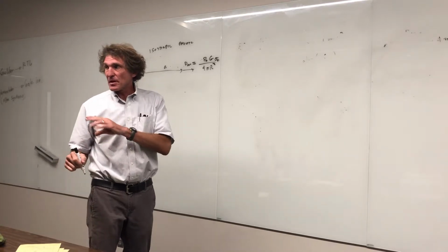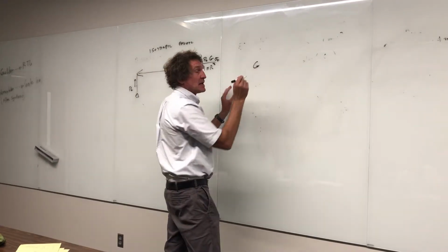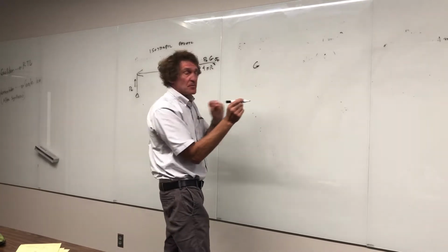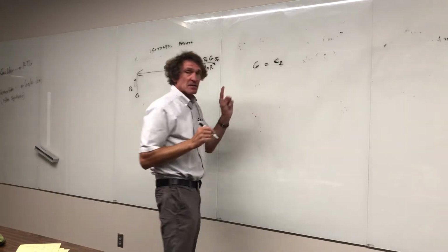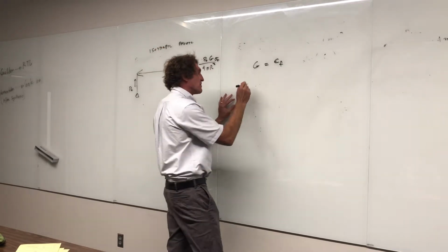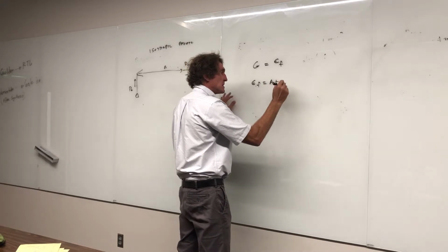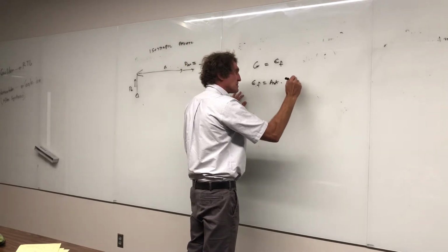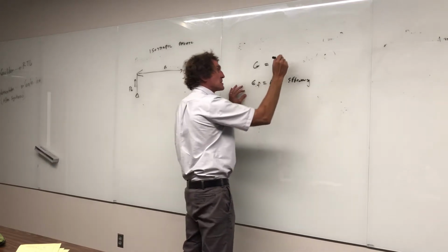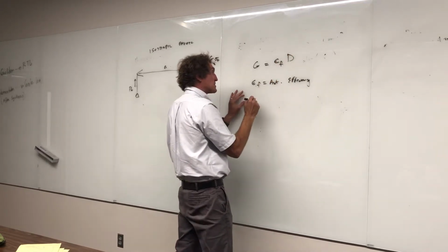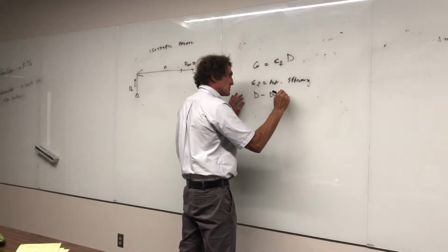First, let me say that gain, the term gain, is really composed of two things. It's composed of something called the antenna efficiency, that I'll explain in a second, that's EF, times D, and D is called the directivity.